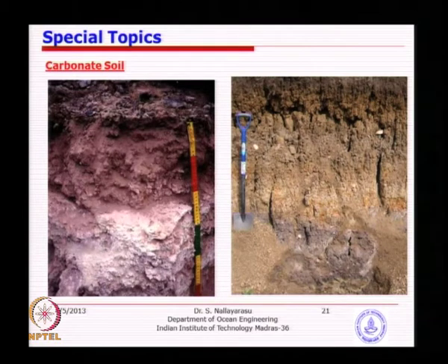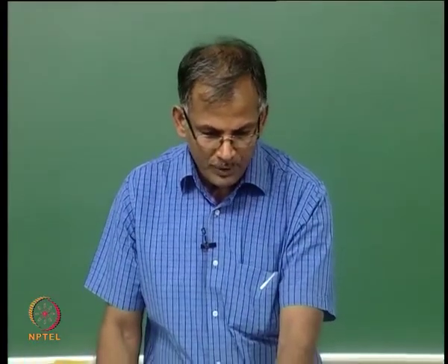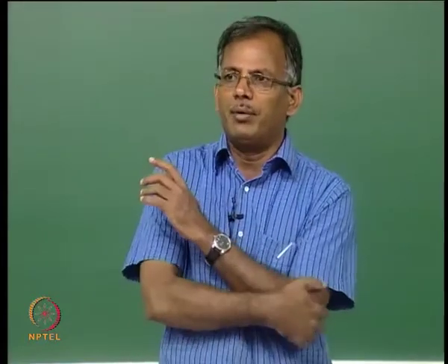So that's one of the areas where API in earlier times had no recommendation. What they say is try to avoid, but for offshore systems, how do you avoid? If you have a place with larger calcium carbonate, we don't want to shift the offshore platform to another location, because that is where the oil is available. So we still have to construct, but in many cities, if you find this type of soil, people don't go for pile foundation, because potentially it can cause trouble at any time, and there is no easy method of treatment available for such soils.